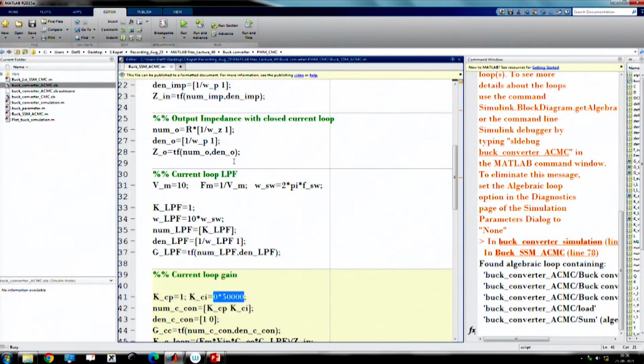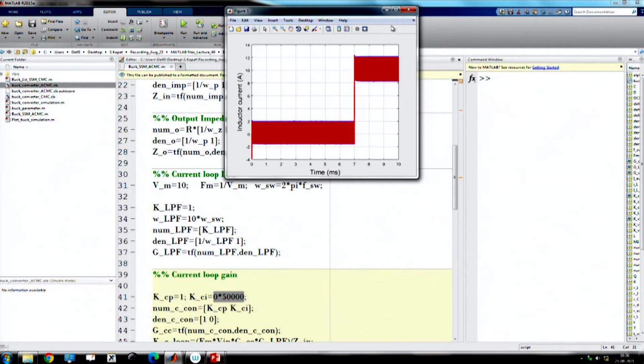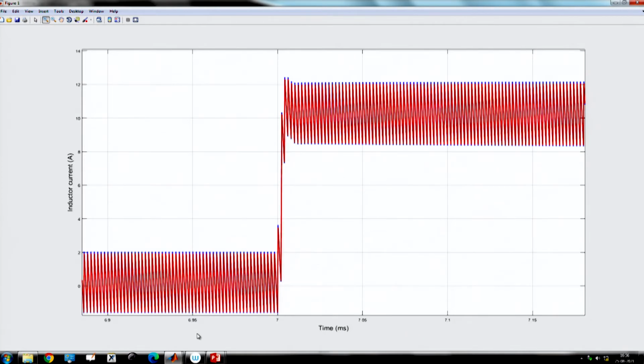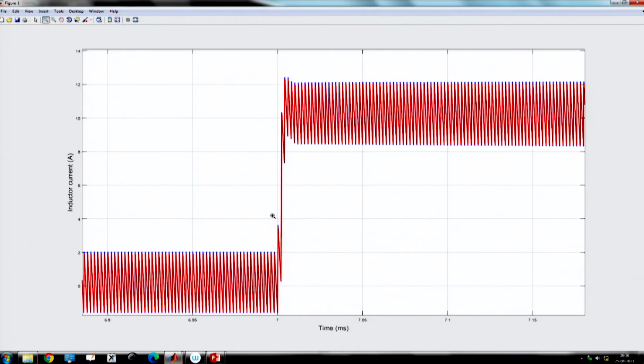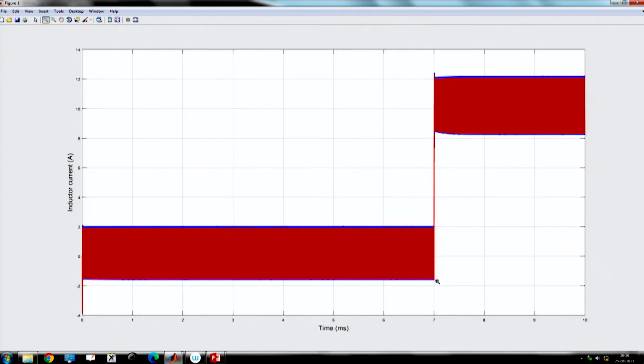what the response of the system is when we choose such a controller. Here we have given a 10 ampere load step. The initial load current was very low. I can tell you that the initial load resistance was set to 5 ohm, so 1 volt by 5 ohm is 200 milliampere. So, it is changing from 0.2 ampere to 10.2 ampere. Okay. Now, what are we going to show here?